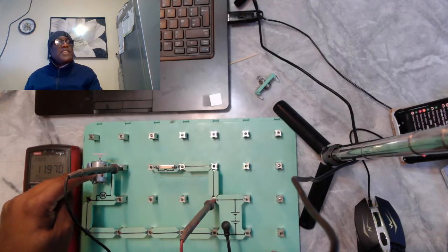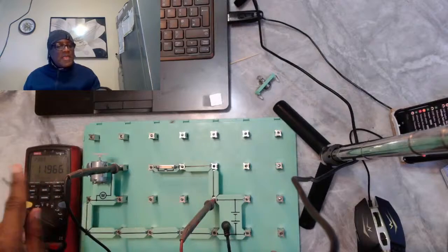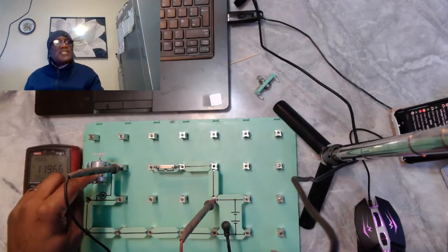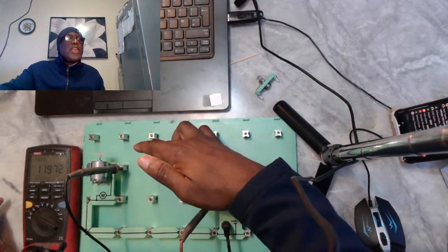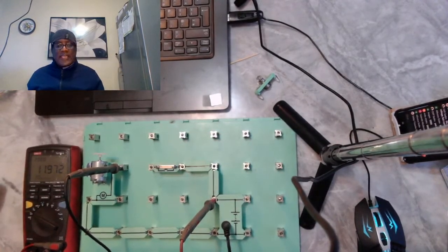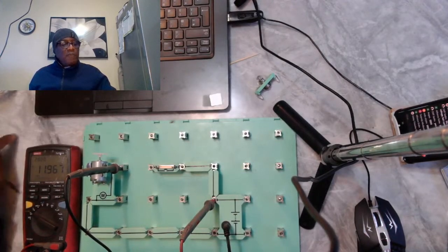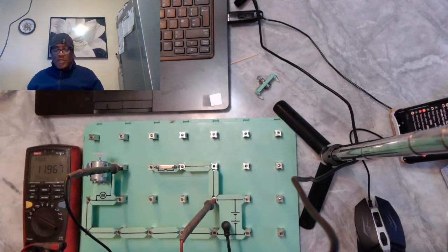Ground has gone through that motor. There's no longer resistance in this motor. This is just becoming one of the conduits. There is no resistance to consume the voltage, because we do not have a complete circuit. So I have proved to you that you will only find voltage on the side where your open is. When you go positive to positive, 0, negative to negative, and then you find your battery voltage there.